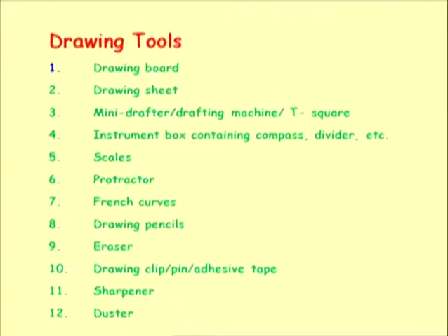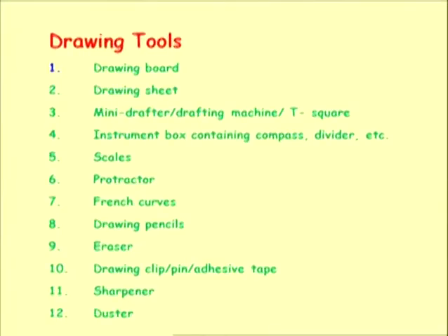Then sharpeners, to make the pencil's lead point very sharp as per the required thickness of the line, we may use the sharpener. Then the duster is to clean the surface of the drawing sheet, and the front face of the pencil also has to be cleaned, so that the lead powder attached to the pencil is not transferred to the white surface of the drawing sheet, leaving unnecessary or undesirable stains on it.